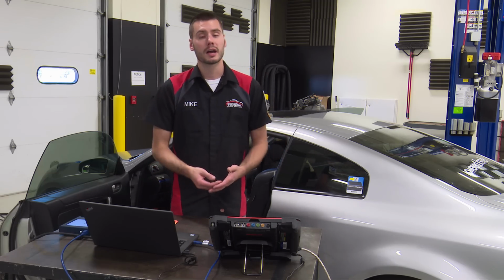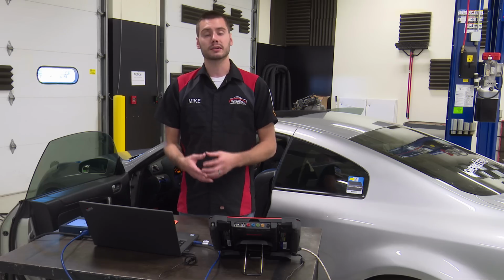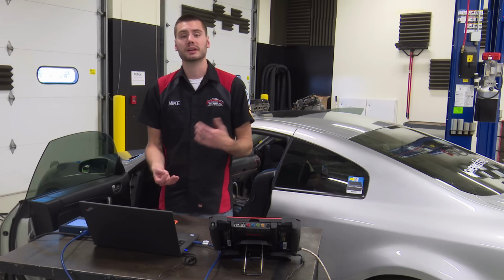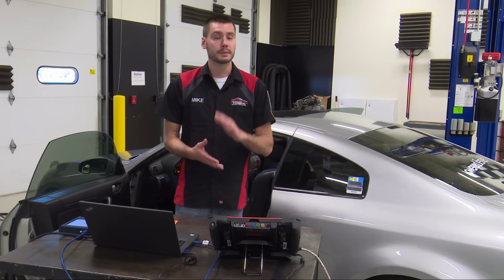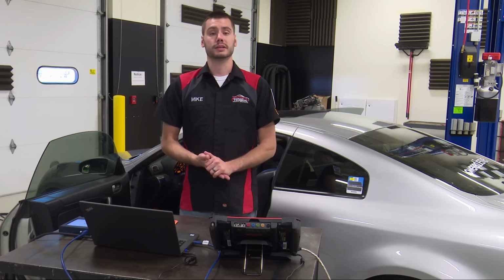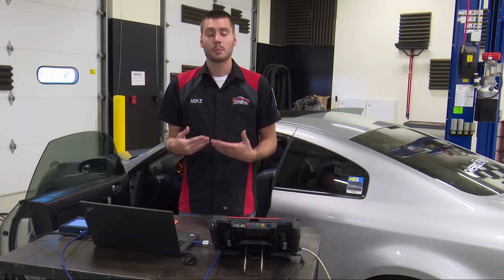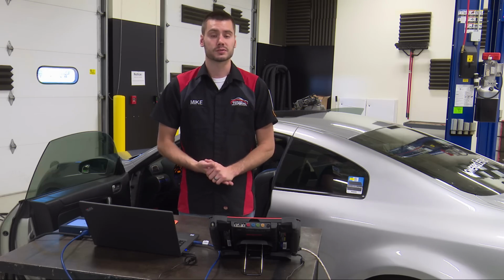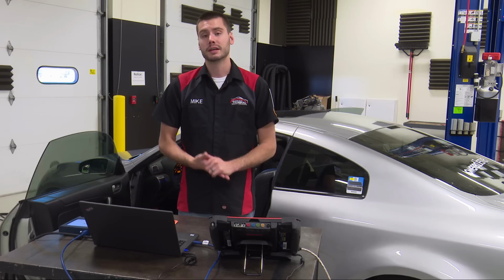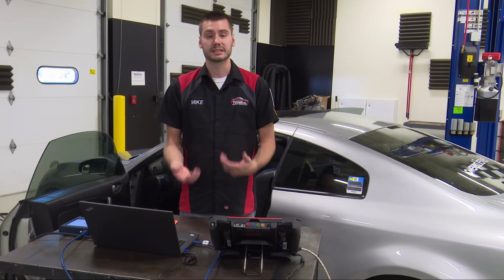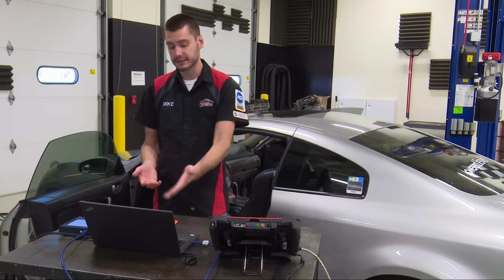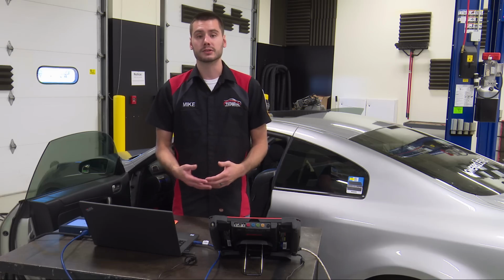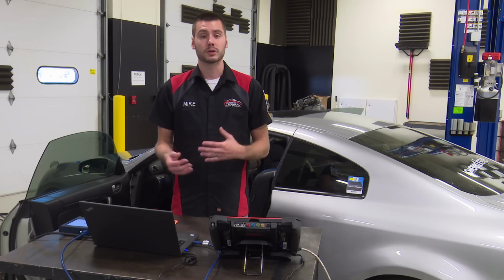Just like a blower motor and a blower motor resistor, it's very rarely the resistor's fault. It's taken out by the blower motor. Well, same thing here. This window motor has taken out our switch. Now, he put himself a nice high quality switch in there, one of our switches, but he didn't buy a high quality motor. He went out and shopped on price for his motor and found a very cheap motor in comparison to a high quality part. It was significantly cheaper. And it's directly reflected in the current that motor draws. It is a dirty part that is going into a computerized circuit. The window switch is computerized.